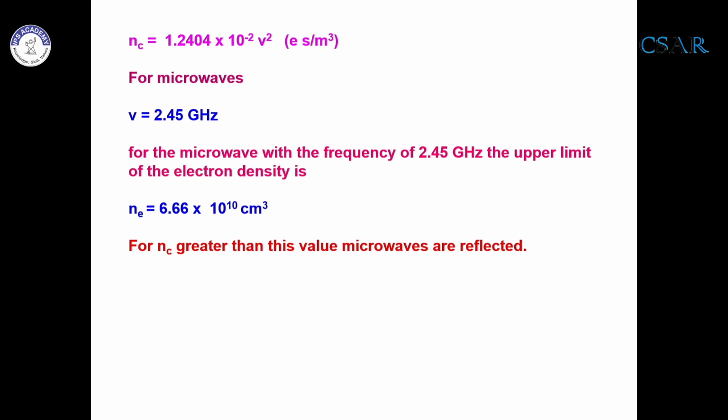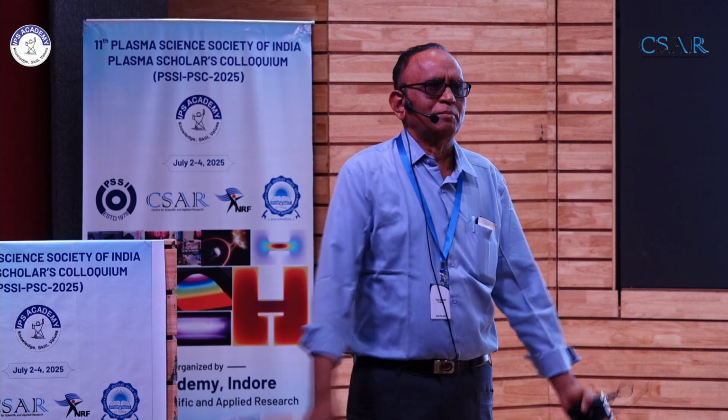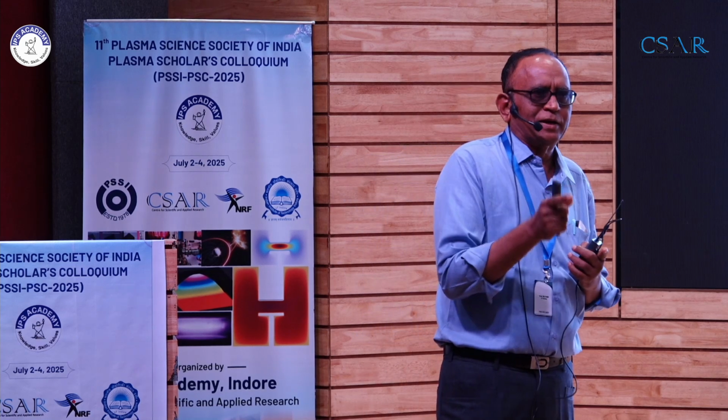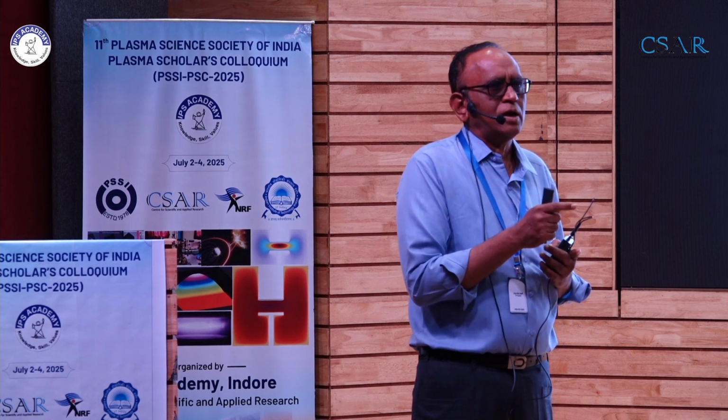Now, what is happening? In earlier days, semiconductor technology was dominated by microwave ECR sources. Recently, ICP has taken over. Microwave ECR sources give a good amount of uniformity, but there is a magnetic field present, and because of this magnetic field there are charged particle damages associated with the growing film.